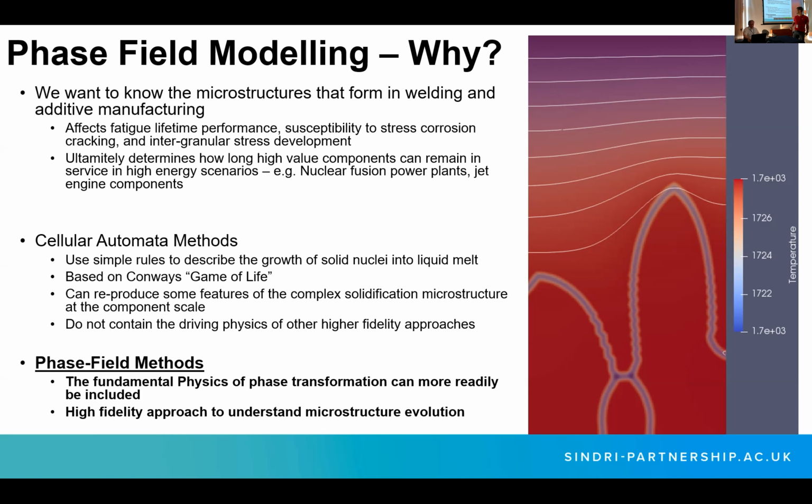the solidification structures. But phase field models are a lot more physically justified, fully thermodynamically informed. And the really neat thing about phase field, the reason to do phase field modeling, is you take a surface description of the free energy, which is really not well defined, and you convert it into a volume integral. So it's a really powerful technique.